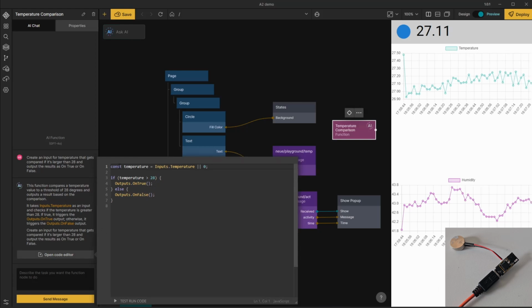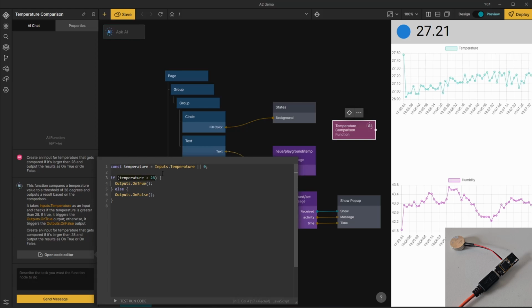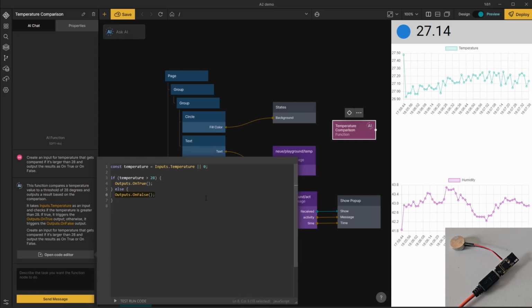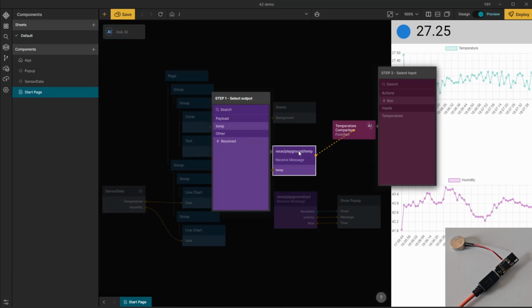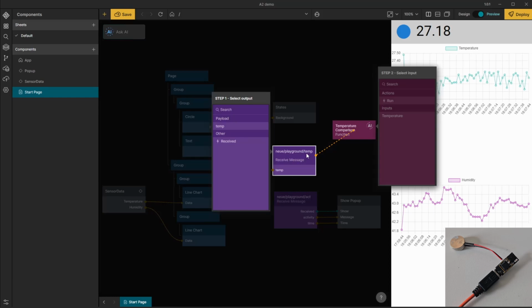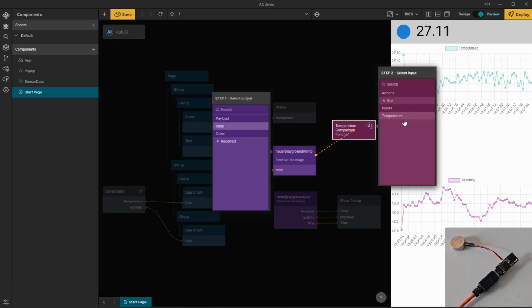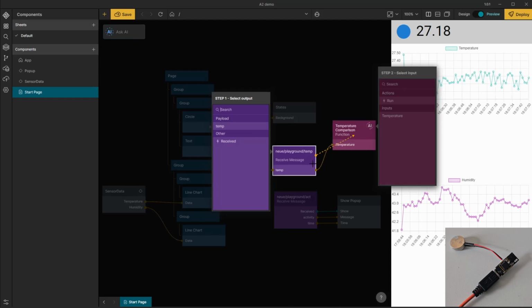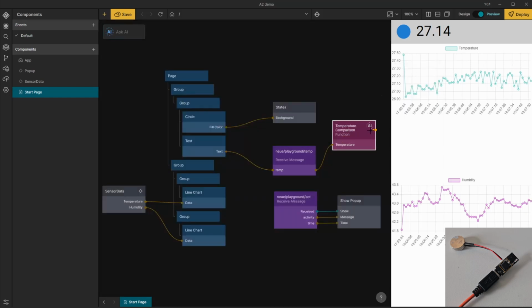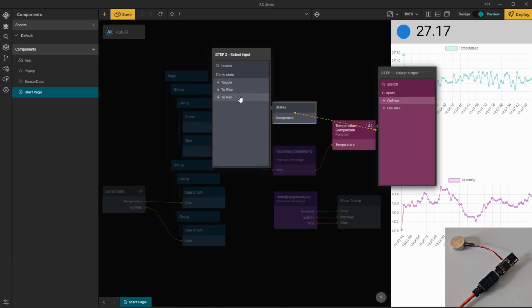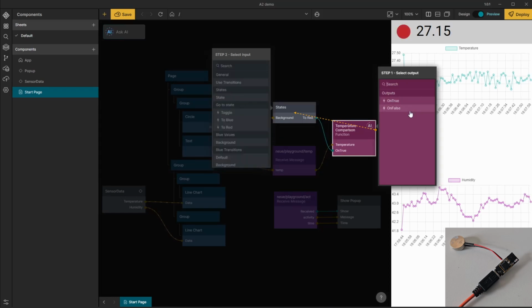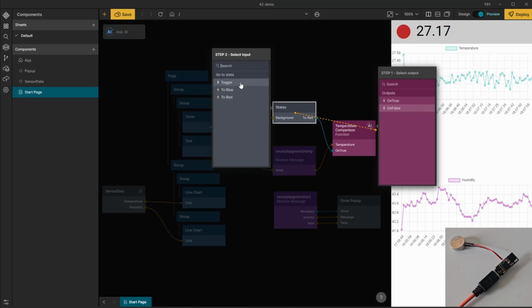And we can see here that we take a temperature value as an input. We do a comparison, and if true, we send that as one output. Otherwise, we send it as another. Now, we can easily hook this up from our telemetry patch that receives the temperature. We can connect the temperatures from output to input. And then we can take that, and on true, we want the circle to be red, and on false, we want it to be blue.